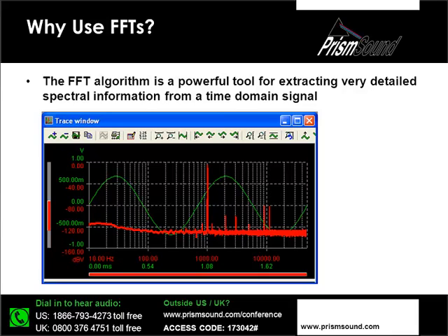realization of the signal. The spectrum, on the other hand, gives us potentially a lot more information, and we can see that in addition to the 1 kHz fundamental here, we can see information relating to the harmonic distortion products. We've got some intermodulation sidebands here either side of the fundamental, and we've also got some intermodulation artifacts happening at a higher frequency as well. And these low-level artifacts are easily revealed in an FFT spectrum, but are, for all practical purposes, invisible when we look at the time domain signal.